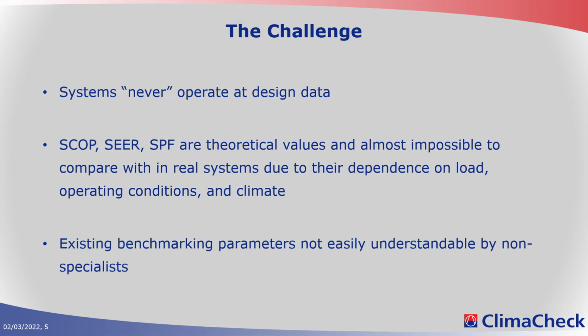because the COP will change depending on the load, depending on the operating conditions, and the load itself will change depending on the operating conditions. So the existing benchmarks that we have, the COP and seasonal COP, are not easily understandable and they cannot be used to compare two systems.